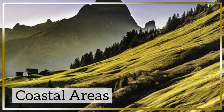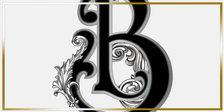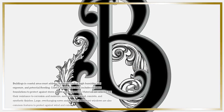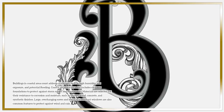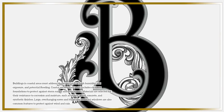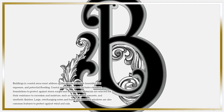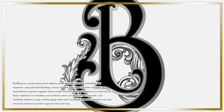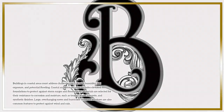Influence of geography. Coastal areas. Buildings in coastal areas must address challenges such as high humidity, salt exposure, and potential flooding. Coastal architecture often includes elevated foundations to protect against storm surges and floodwaters. Materials are selected for their resistance to corrosion and moisture, such as treated wood, concrete, and synthetic finishes. Large, overhanging eaves and hurricane-resistant windows are also common features to protect against wind and rain.